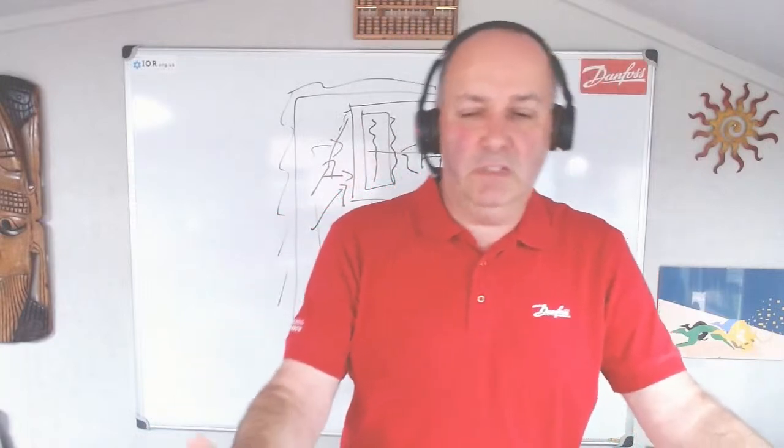Grindstone, nice name. What temperature do you recommend for terminating a fan delay? I was always taught sort of -5, -7, and I guess you're talking snap freeze on the evaporator. So around about -5, -7.